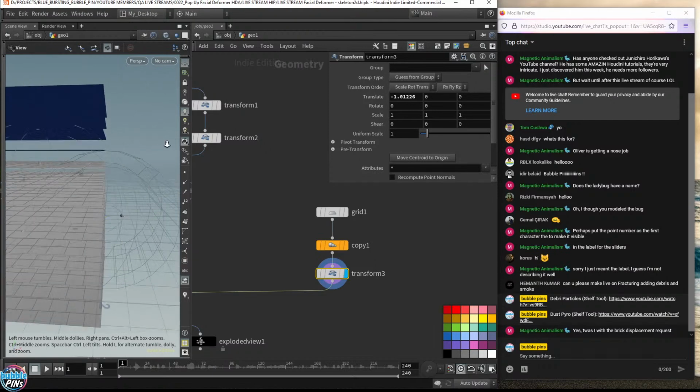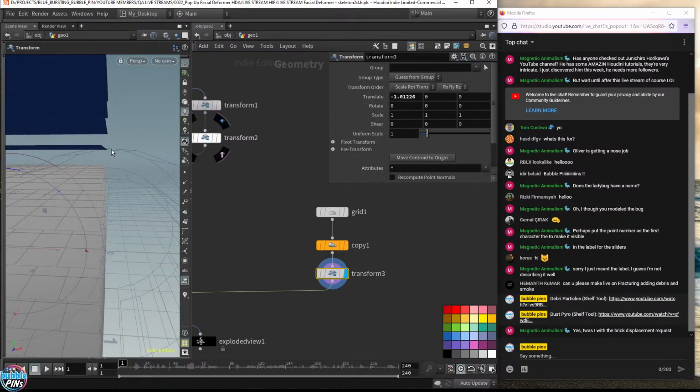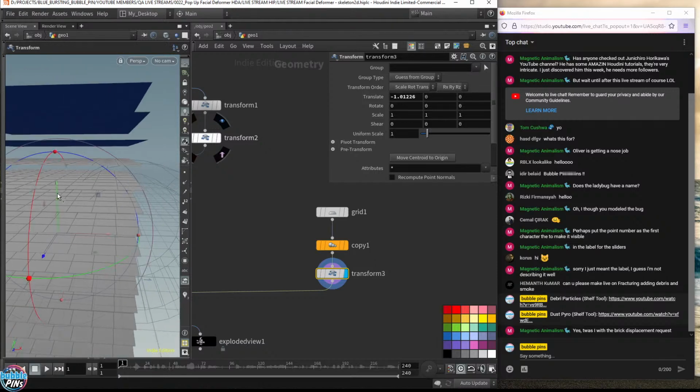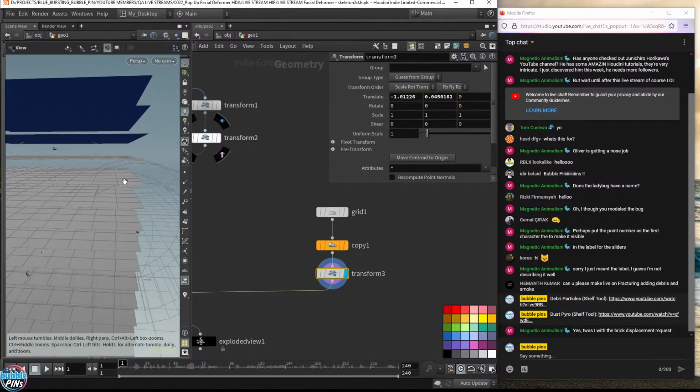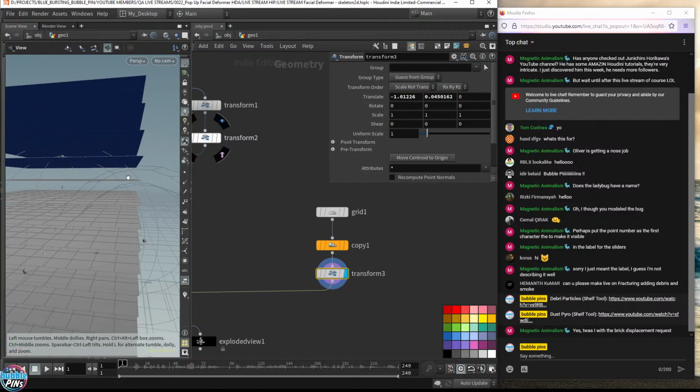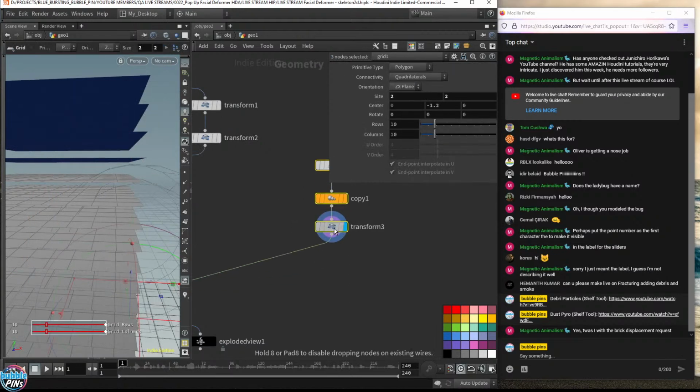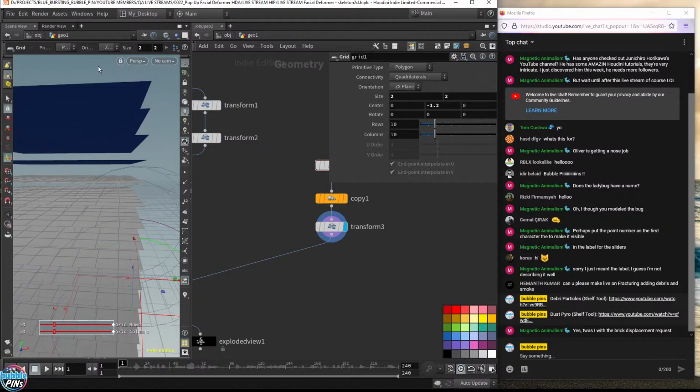This upper part, you can see that this grid is exactly right there. So it's slicing it. It's not slicing all the way through. That may or may not cause a problem with the Boolean. The Boolean doesn't really like stuff like that. It only likes it being sliced all the way through. And it won't look right either. So in order to simplify this, I'm just going to delete that grid.